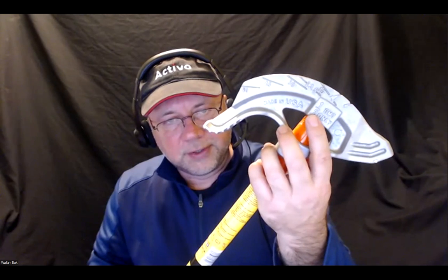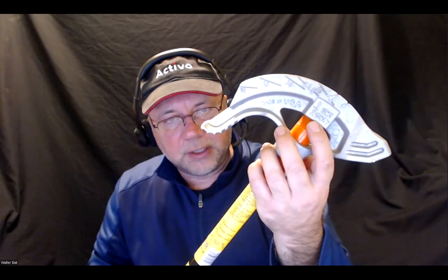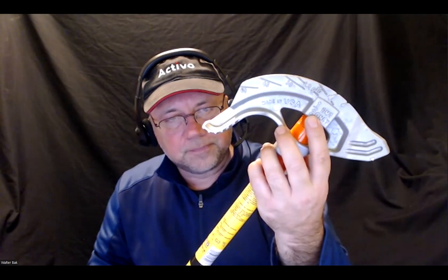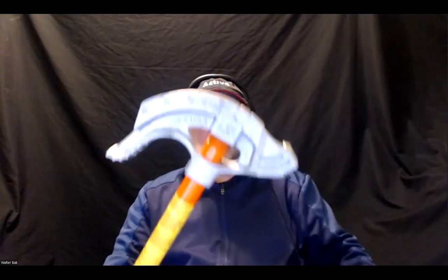This one says it is 1/2-inch EMT only. In our lab, we also have the 3/4-inch EMT, which is going to be a little bit wider shoe here, because the 3/4 is thicker in diameter than 1/2-inch.